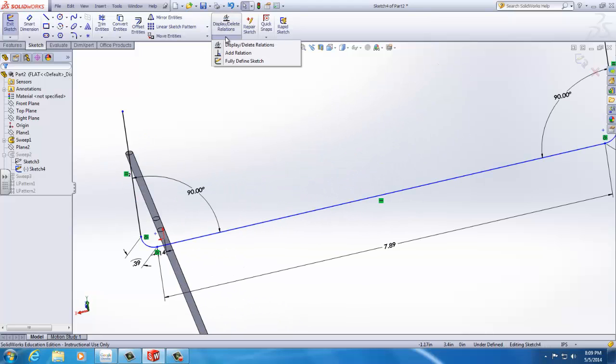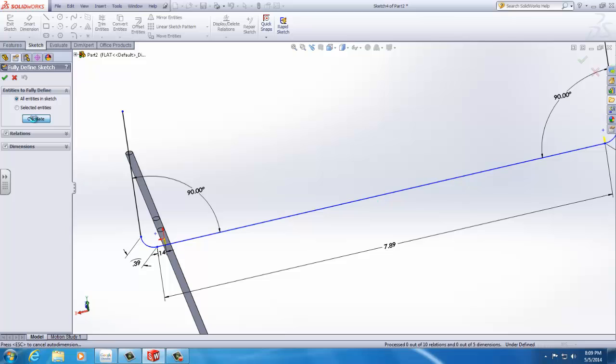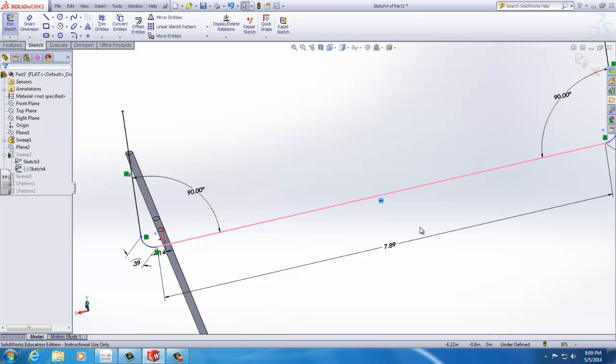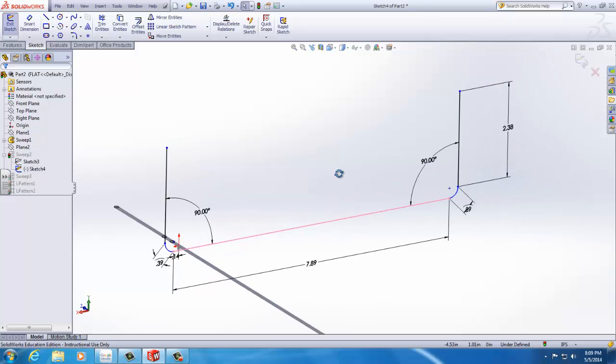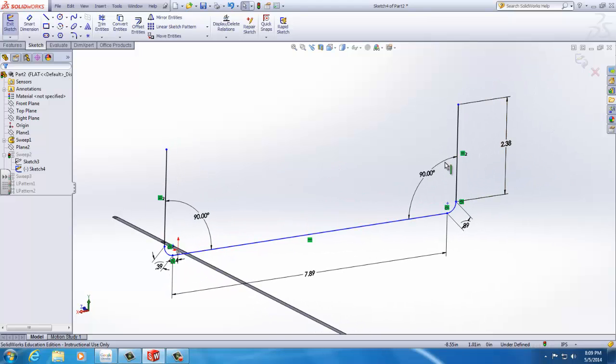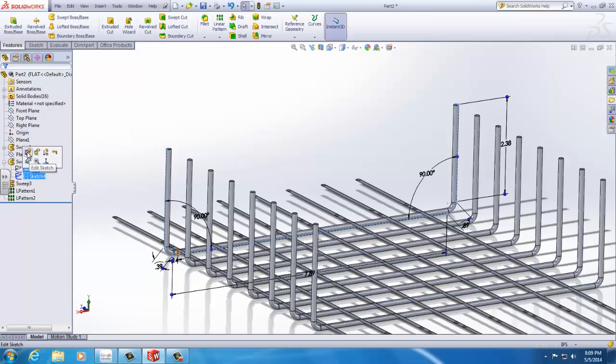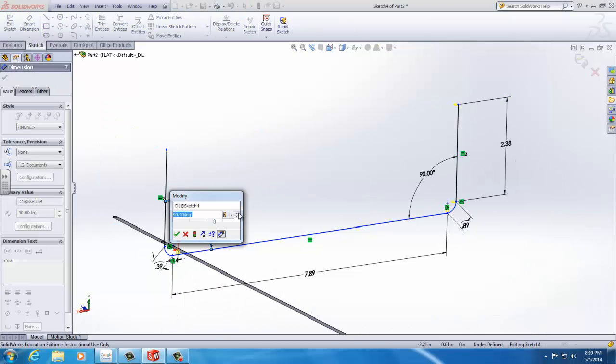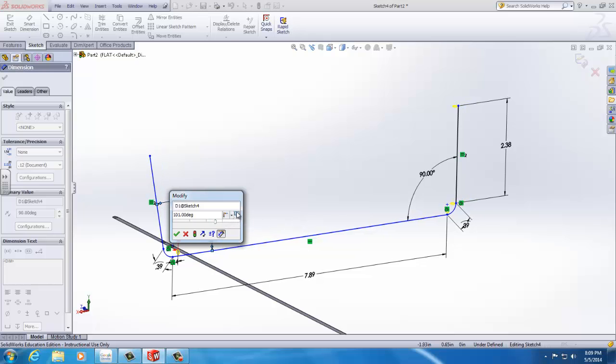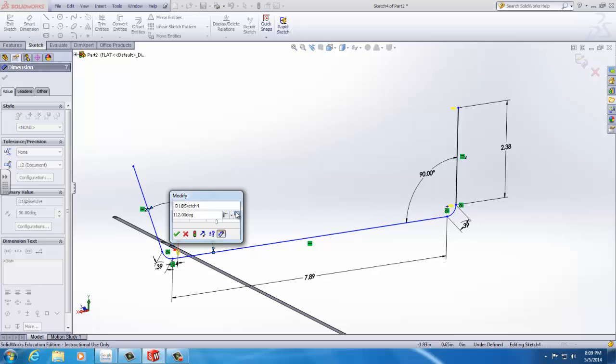So, we're going to do mirror. Mirror will be the front plane. The body would be the surface that we have created, and not the one I thickened. I think we should be okay now. And then we do the thicken parts. Hopefully it doesn't crash. Hopefully there's no error. But, who knows? Oh, it worked, perfect. So it actually has a thickness, you can barely see it, but it's there.